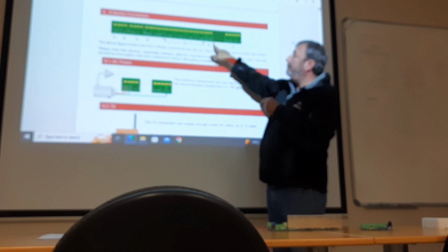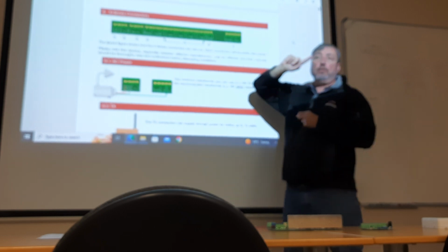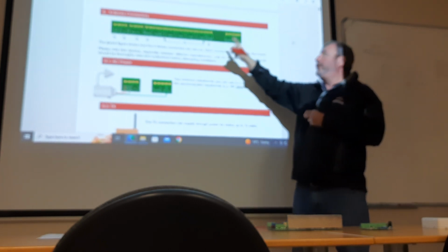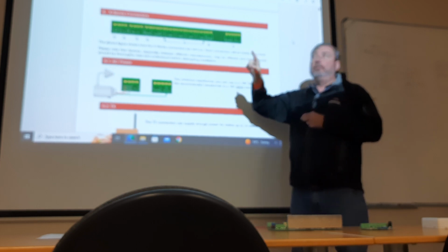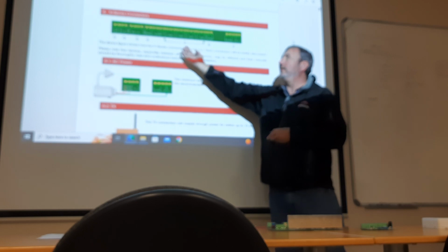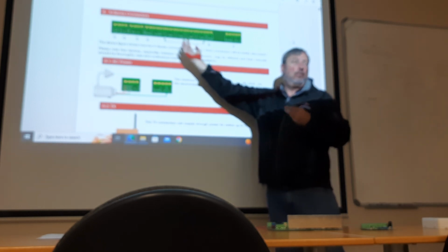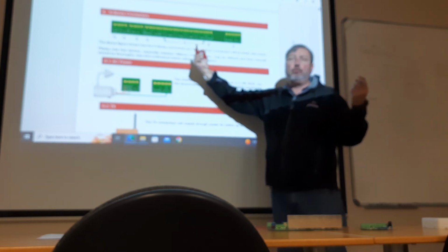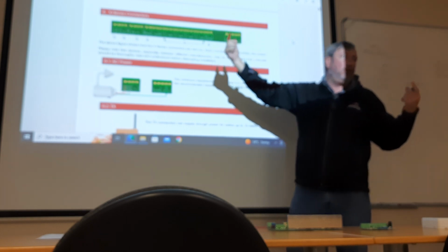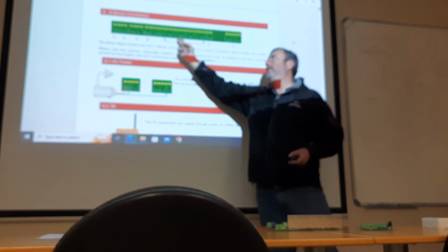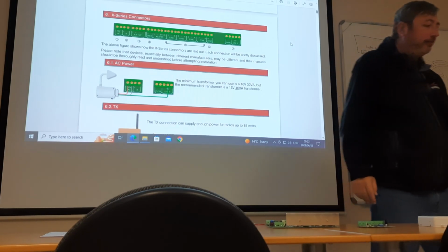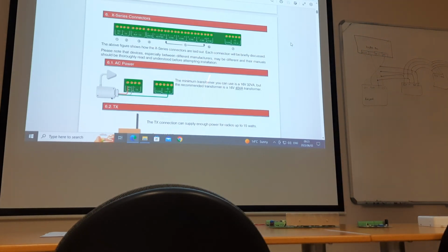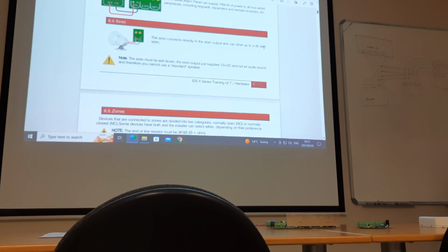And you'll see there is a dedicated panic zone that you can go and put a panic button on. They just made it so that you don't unnecessarily take a zone up for just a panic button. But I mean, you can add more than one panic button on your panel. Then you're going to use maybe one of those zones for the panic button. But that one is just to save yourself space. And then, like we said, your phone line for your landline monitoring.